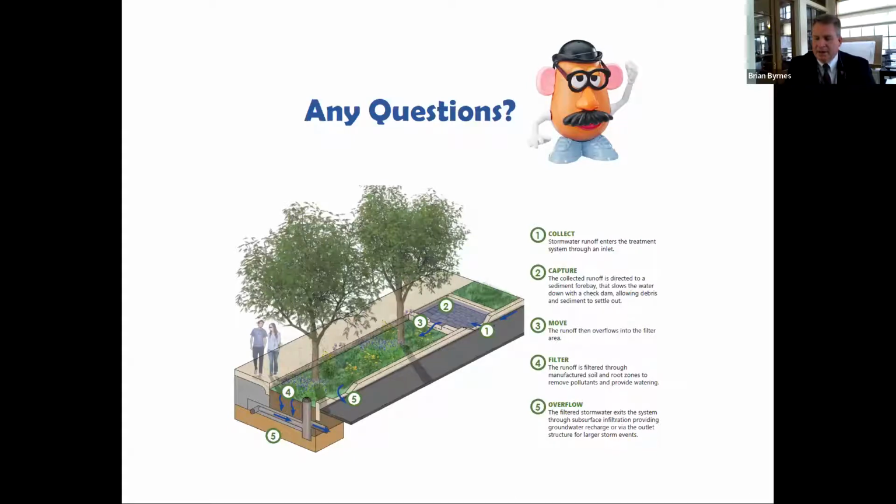We do a lot of training in the Providence Parks Department, and our crews are now well versed in the type of practice that we install here. But we don't have a vac truck. DPW does, but we don't have access to it every day. So we don't build things that require that. It's really important because oftentimes the cost of the construction is far less than the cost of the maintenance. And if these aren't functioning after 3 to 5 years, which is the lifespan of some stormwater retrofits, where there's sediment or other things that are going to clog it up or make it non-functional, those costs can be much more expensive over 20 years or 30 years.